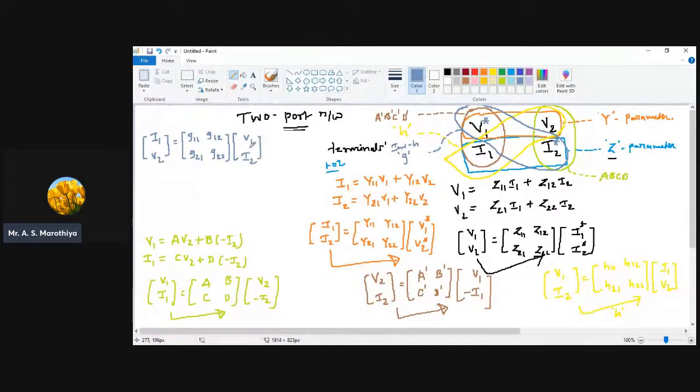This is very important. Here we have taken one parameter from port 1 and another one from port 2. In the same way, this is from port 1 and this is from port 2. So we are defining I1 and V2 in terms of V1 and I2. It is a combination of hybridization, and because it is inverse, you may take this as the inverse H parameter, or sometimes it is also called the G parameter. Now, because we have only 6 possible conditions and no possible conditions are remaining, we have only 6 different types of two-port network.